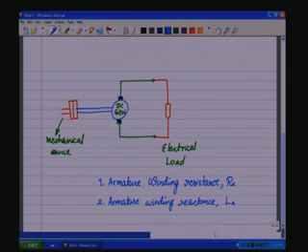If on the electrical side the voltage is DC and the current is DC, there is no dynamics involved, and the reactance component does not come into the picture because omega is 0, so omega L is equal to 0. But whenever there is any step change in the load, a change in the excitation, or a change in the generated EMF, any change is going to cause L di by dt, and that counter EMF, or that L di by dt portion, is going to lead to a dynamic situation, and during those conditions LA will come to play a role.